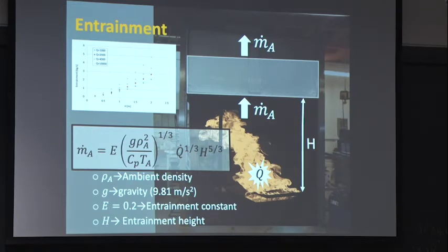Is that okay? So effectively, if you do it all correctly, what I wanted to show you was that the gravity, the heat release rate, they come to the 1/3 power. Okay? And that's the empirical correlation. So you know that they're proportional to that, and the constant of proportionality comes out as 0.2. Okay? Because obviously I'm only scaling, so the number is not correct. Is that okay?